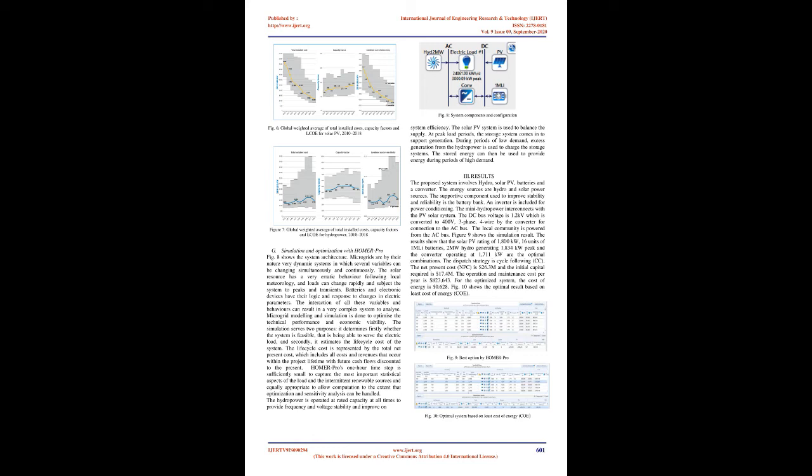Batteries. Batteries are an integral part of hybrid renewable energy systems. The battery backup adds stability to the network by storing energy during peak generation and releasing the energy for peak consumption when there is insufficient generation from renewable sources. The battery considered for the project is a lithium-ion 1 MWh capacity battery with supplier integration into HOMER Pro. The specifications and price are provided in the software. The battery model parameters are shown in Table 2.